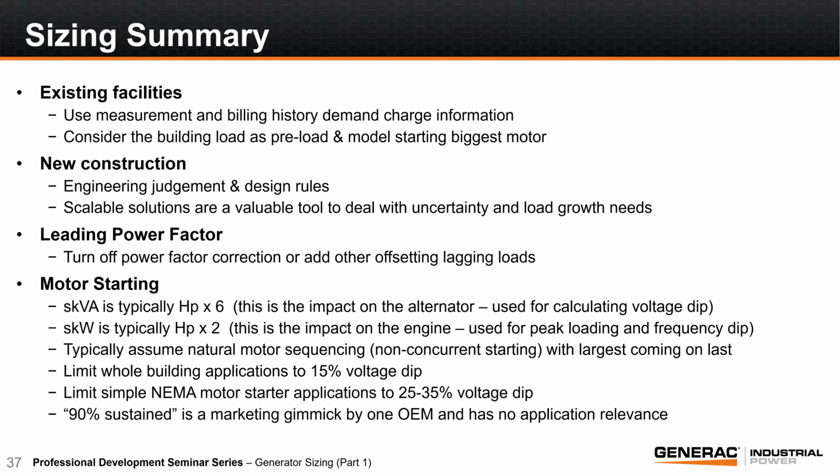Right. Another thing is looking at it strictly from a distribution standpoint. You need to put the distribution in place today. Even if you're going to expand and add more generators later, you want to make sure you put all the distribution in place now. So all you're doing is adding generation to the system. It's more of a plug and play system, as Amy mentioned, right? The generators are already ready to parallel. It's just dropping a unit down, tying it with the others, and it'll sync in and do its thing.